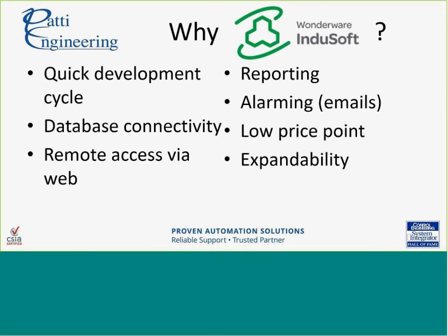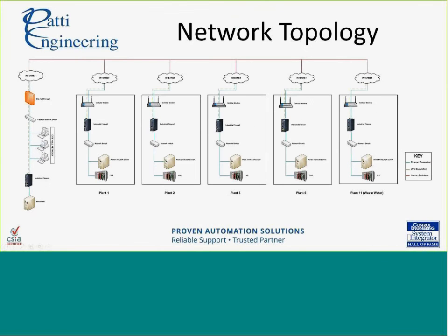It's also got a pretty good price point. So for the entire system, we actually had 5 different installations of InduSoft, and that was for independent local control at each plant. We didn't want a loss of network connectivity to remove their ability to control locally. So we set up an instance in InduSoft on each location, and with the price point that they offer, it wasn't that much of a hurdle on that point. And then expandability, you can always buy what you think you need as far as licenses, and if you need to step up, you just pay the difference to that next level.